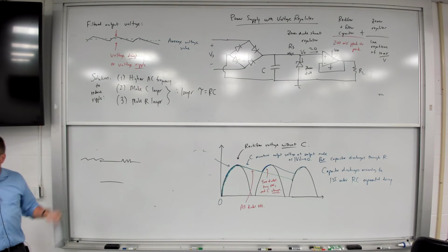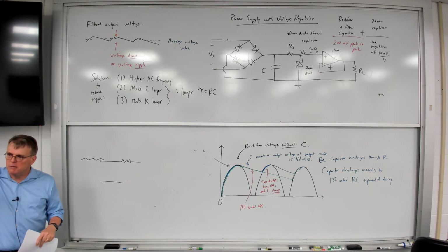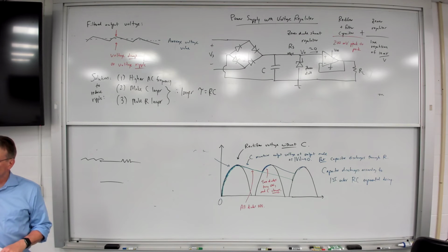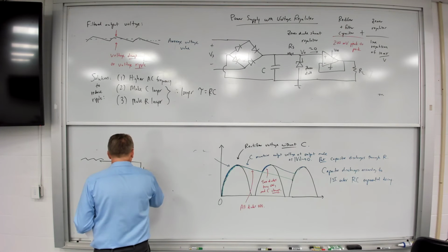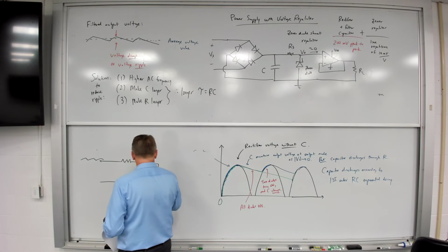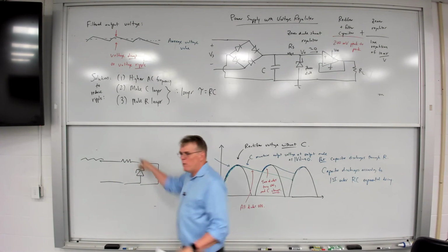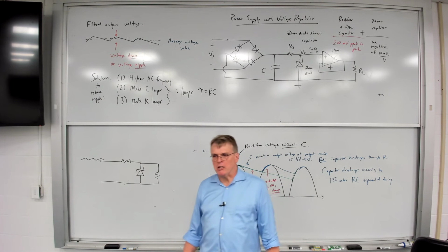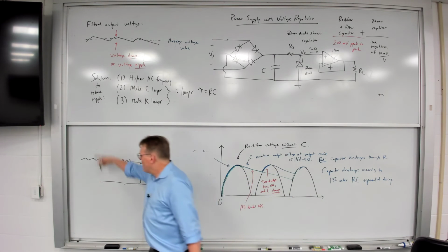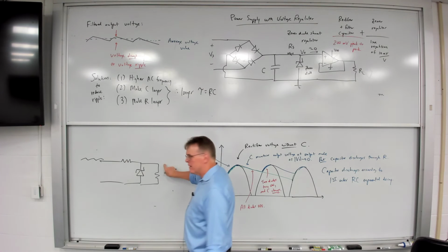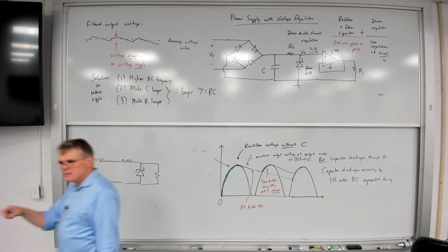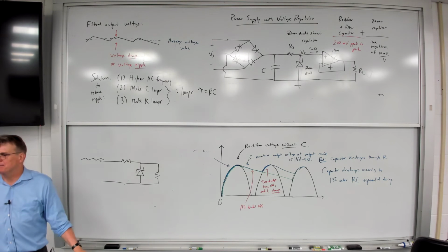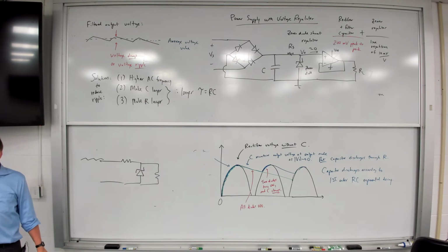So what does a shunt regulator do? It takes a varying input voltage and keeps that output voltage stable. We did those calculations before. Remember how we calculated line regulation. A large input swing causes a very, very tiny change at the output. So we've already covered this exact concept. This is no different. This is line regulation in a voltage regulator.